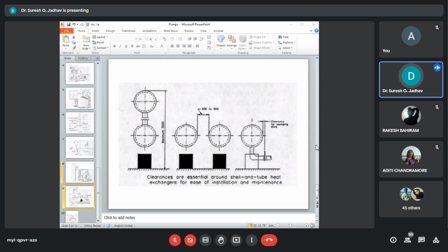The pipelines with valves and control valves should run along the access aisle close to the exchanger. Pipelines connecting the exchanger with adjacent process equipment can run point to point just above required headrooms. The steam lines connecting the header on the rack can be arranged on either side of the exchangers. Valve handles should be made accessible from the grade and from accessway.